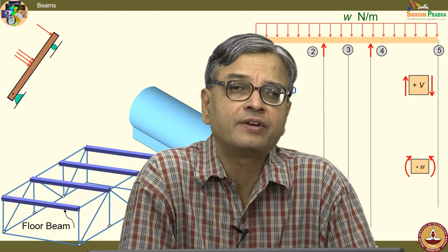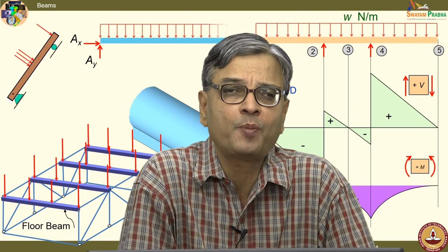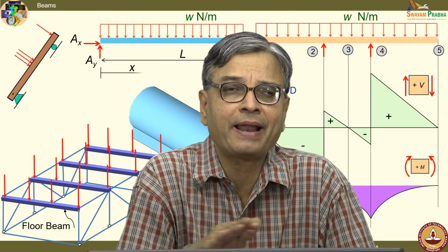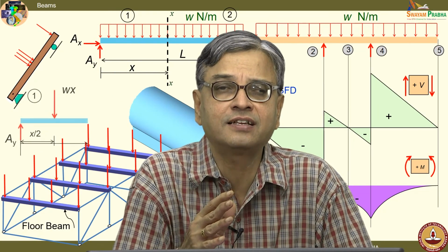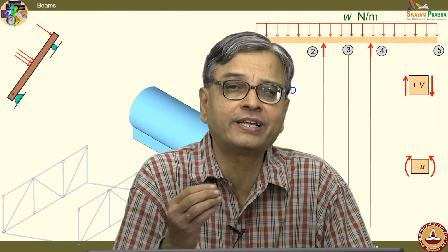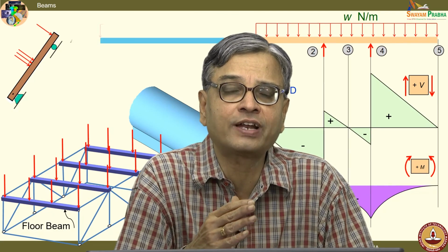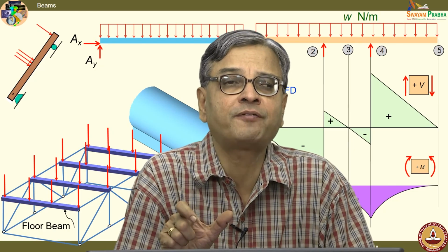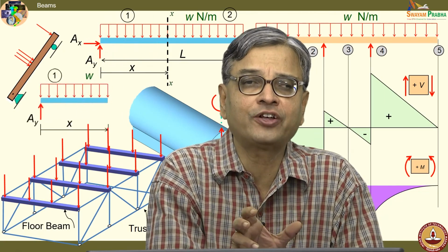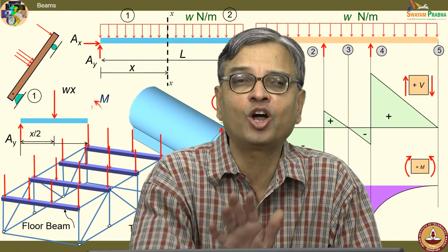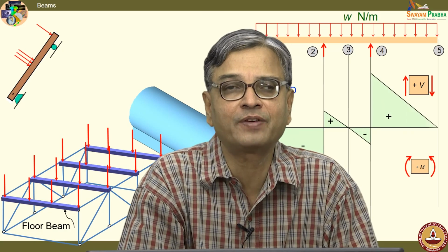So, in this class we have determined what is the optimal position of supports for a simple problem of arranging books on a plank. In the process, we learned the sign of the bending moment is not of that concern, only the magnitude is very important. That knowledge you derive from what you see in strength of materials, and we have used that as a criterion to write the optimal condition and determine the distance between the supports. In a sense, it tallied very closely to our intuition, but from a purist point of view, it is not exactly intuition. You need the elaborate theory of bending of beams to identify an optimal location correctly. So, that is another way of looking at it.